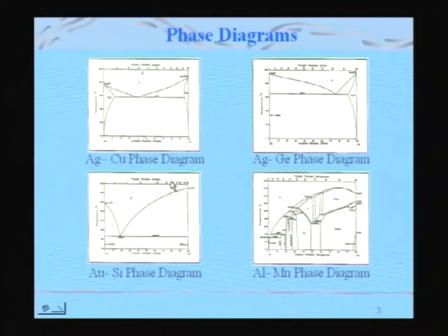And then he took this gold silicon, which is again a eutectic, and if you compare the gold silver copper with gold silicon, you can clearly see that this is a deeper eutectic than this. Just by looking at it, one can know. You look at the two pure metal melting points and look at the eutectic temperature, compare with the two pure metal melting points in gold silicon and the eutectic, and you can see from here that the eutectic is much deeper than this. And when he took that particular composition, which is about 20% silicon, what he got was a glass.